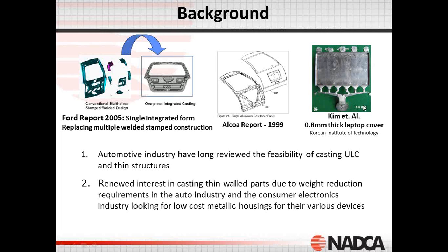In this webinar, we'll be focused on looking at a case study of this part here, which is an example of a laptop case, which is 0.8 millimeters thick. And there is some researchers at the Korean Institute of Technology that did some extensive experimental work to determine what factors are required, what variables are required to successfully cast a part as thin as 0.8 millimeters thick using aluminum. A383 was the alloy they used.